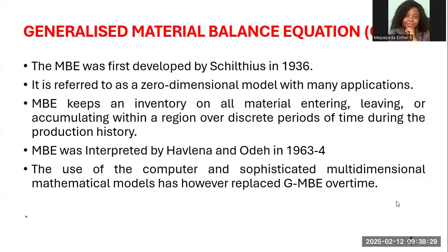MBE keeps an inventory of all material entering, leaving, or accumulating within a region over a discrete period of time during the production history. So the major aim of the MBE, that's the material balance equation, is to keep an inventory of your reservoir fluids leaving or accumulating within the region of your reservoir. Okay, and then in 1963, Havlena and Odeh did an interpretation of the MBE, that was developed by Schilthuis.